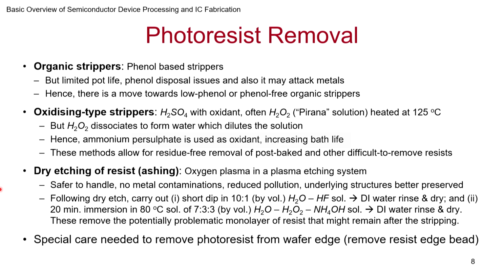Special care is needed to remove photoresist from the wafer edge, as I said, and that actually is a challenge, and people have developed techniques to make sure that specifically the edge of the wafer sees the solvents, so that the photoresist gets removed. Part of the reason is you have bead formation. When you spin coat, it goes to the edge and forms a slightly hillock-type region all around the edge. That's what is known as the bead. That can end up causing particulates, so you have to take special care for that.